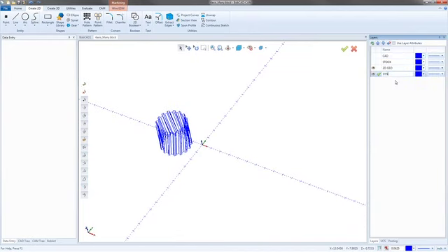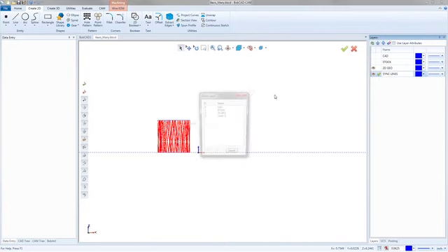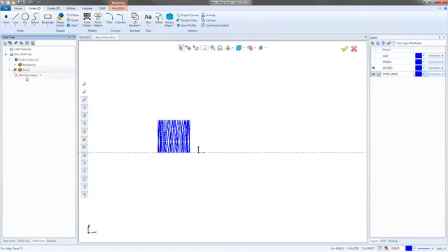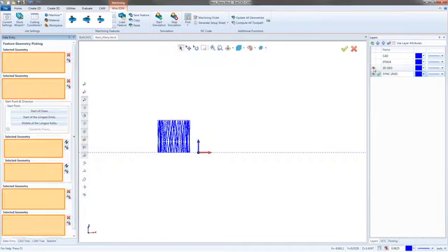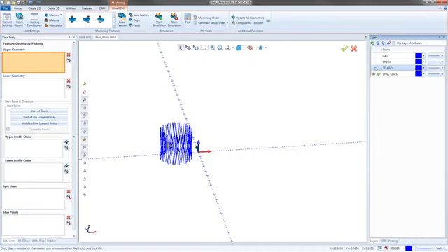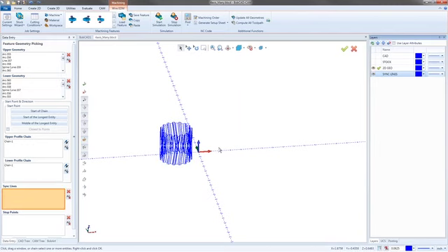Now I'm going to do my sync lines. Front view, drag a box. Again, don't touch the top or the bottom. Modify attributes, layer, sync lines, or whatever, I didn't rename it yet. And then right here, I'm going to start my 4-axis inside, upper profile right here, lower profile right there. This time, I'm going to choose the sync lines, and that's just because they're easy to pick.